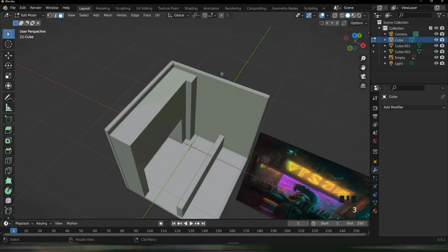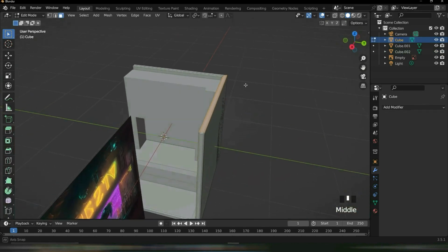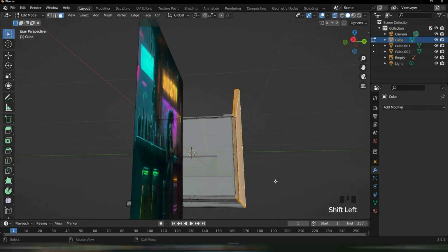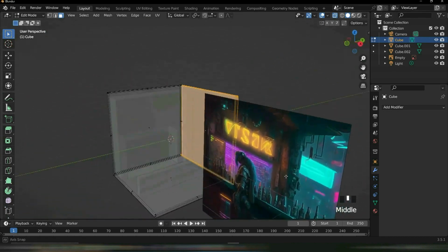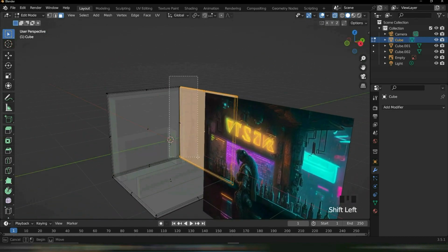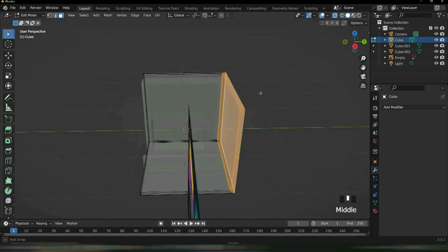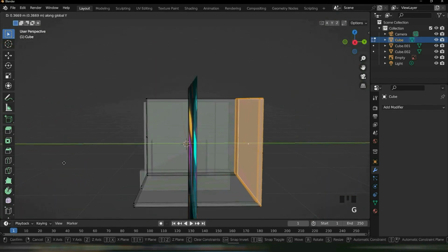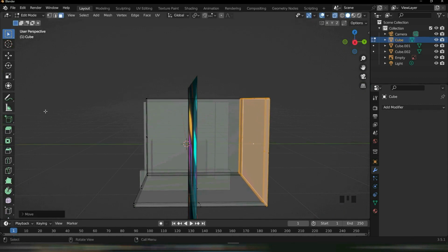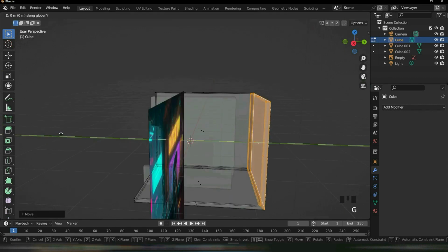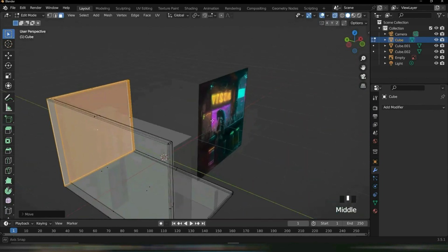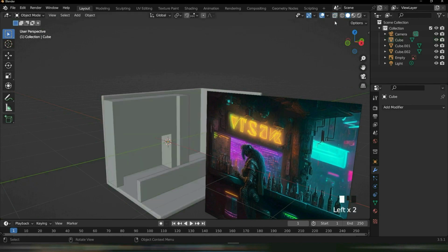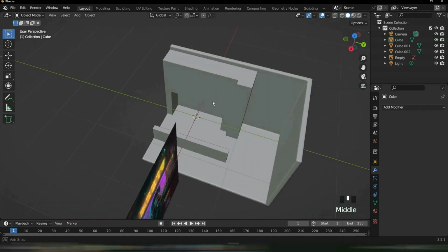and let's do face selection, select these faces here. Let's go into X-ray mode. Let's select these corners here, just so they don't get messed up. I want to select these corners here as well. There we go. Now we do G, Y, and just scale it outwards like this. Keep scaling it outwards, so GY as much as you want to, like there. We're going to add a gap there later on, so it really doesn't matter, but here.